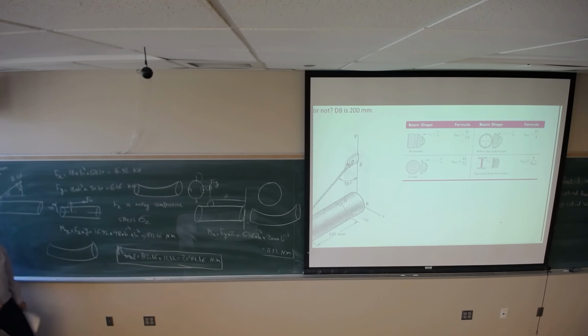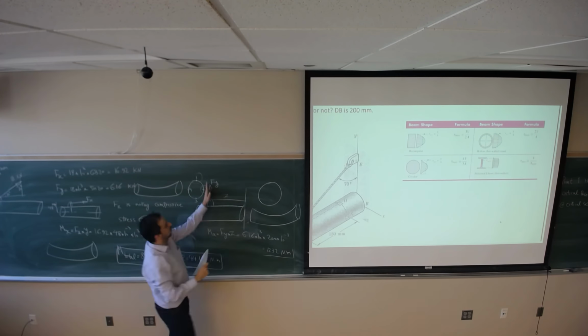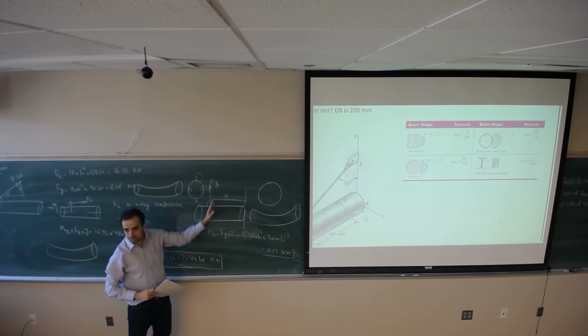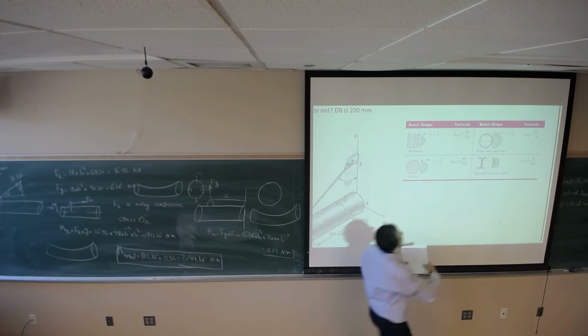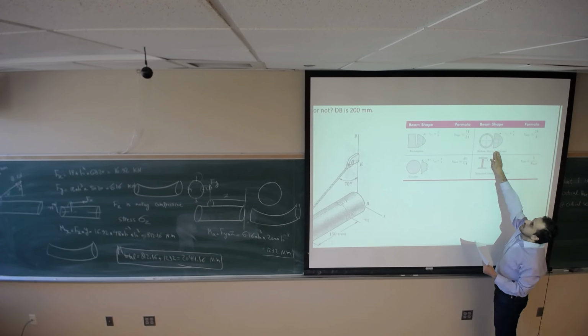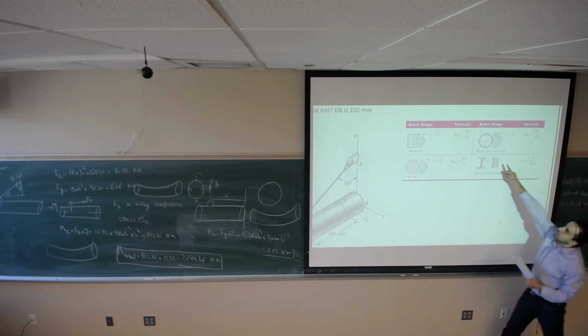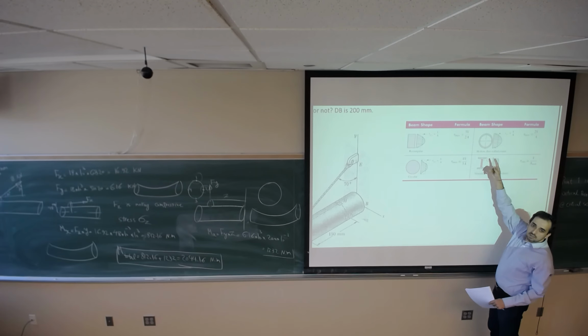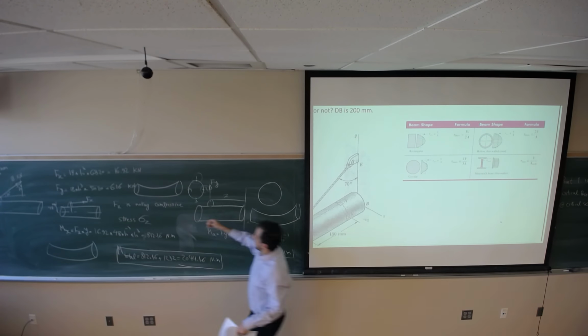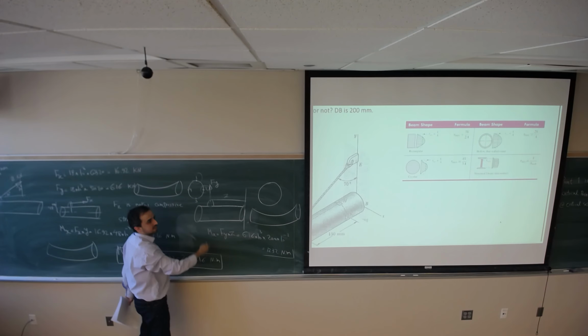What's transverse shear? Quick refresher. If you have a transverse shear force, which is something like this, it's making transverse shear over the cross section. So the maximum transverse shear is gonna be the force divided by area times 2 for the cross section that we have. Is it the force trying to pull it up the wall? Yes, basically, the force is gonna cut the pipe.